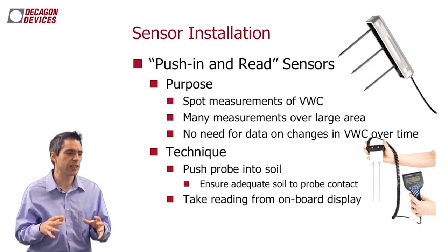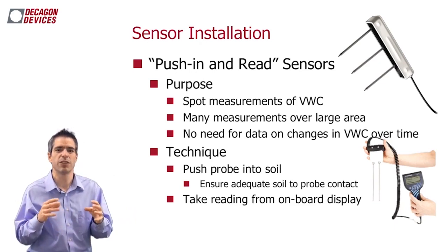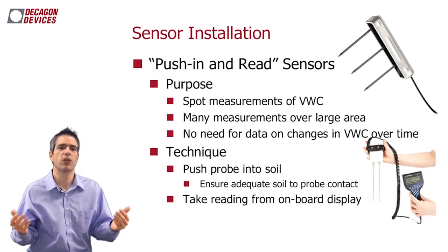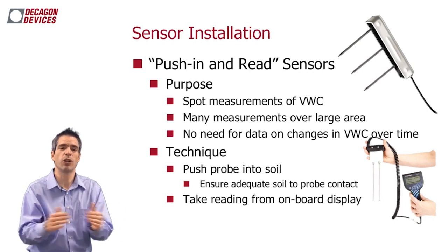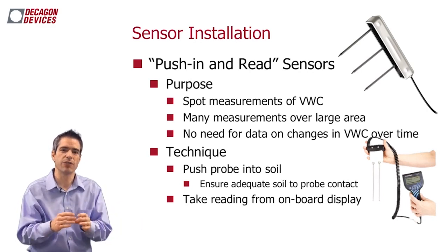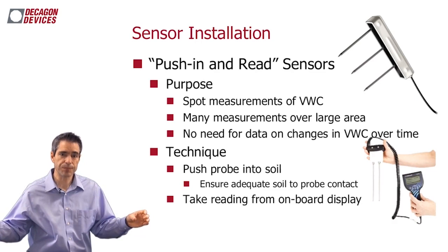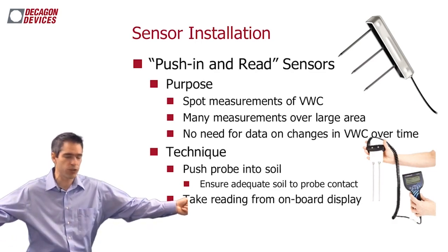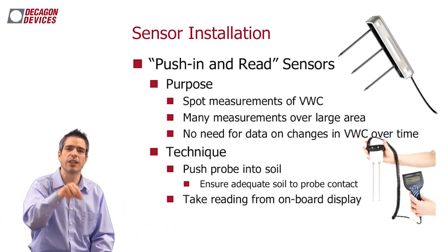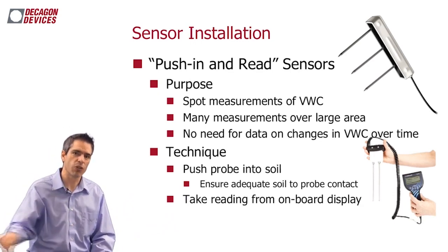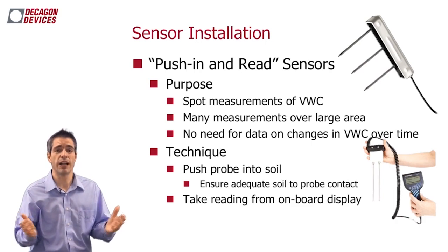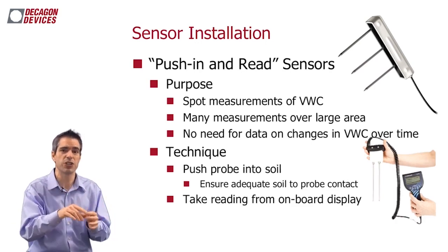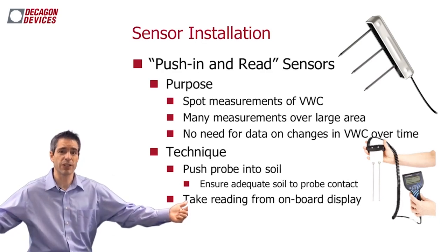My concern with this technique is not the way the measurement is made, but just the validity of that measurement. We've spent a lot of time here just having fun looking at how water content varies in space. And in fact, if you go out, take a long tape measure, lay it out, and measure water content, let's say every half meter across a long transect, you'll find you can create a very interesting variogram, something that tells you the variation in water content across the length of this.